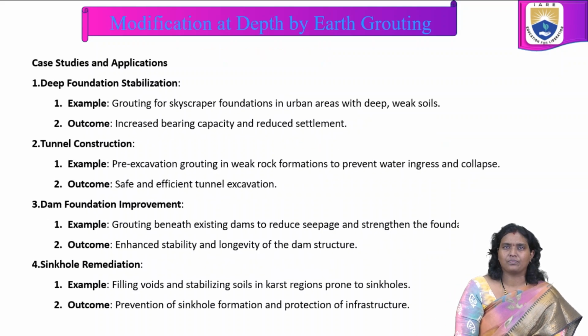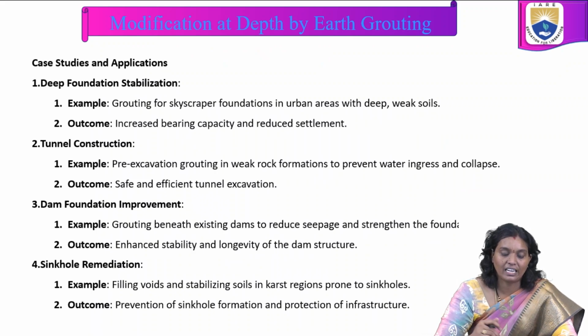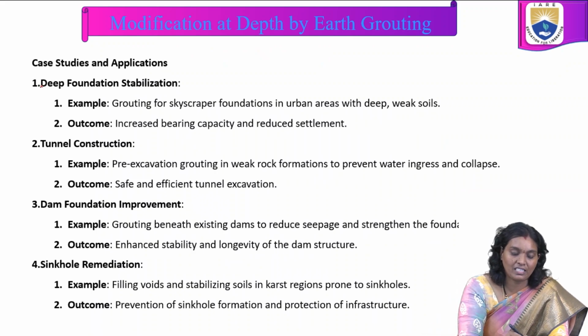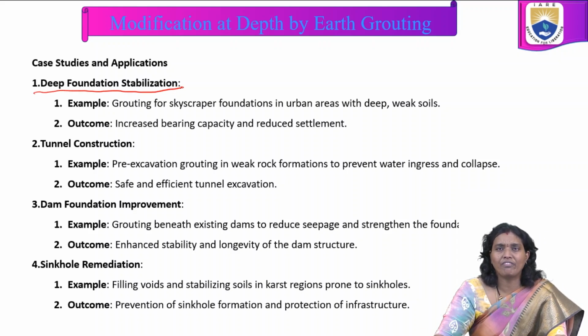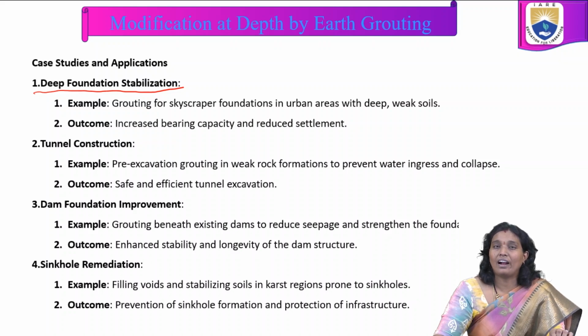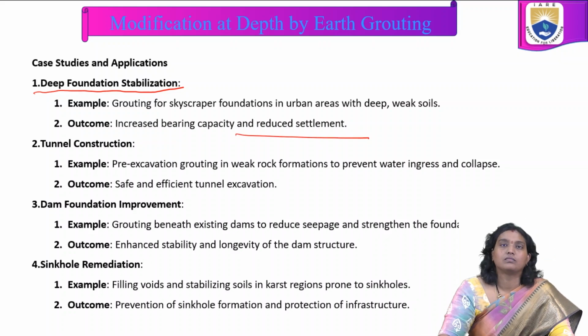Coming to some of the case studies and their applications, deep foundation stabilization is one of the case studies. For example, grouting for skyscraper foundations in urban areas with deep, weak soils. Once we have done this grouting, the outcome is increased bearing capacity and reduced settlement.